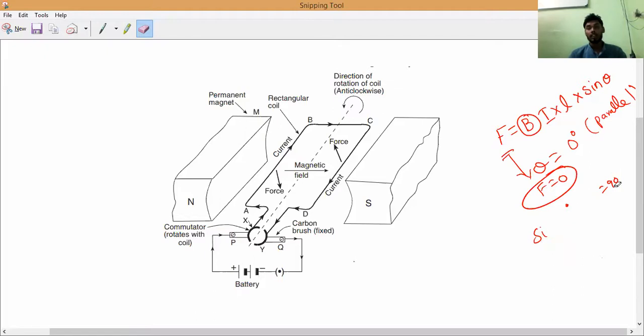Because if you attach the wire directly to the commutator, suppose this is the wire I attach to the commutator, so what is happening, guys? When the commutator is rotating, this wire will also rotate and start spinning on the commutator. Yes or no, guys? Please respond. So this is what will happen. To avoid this, because at a certain stage the motor's wire connections will break.